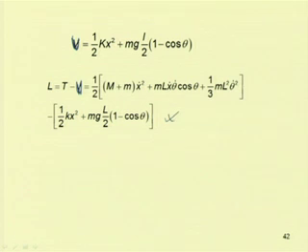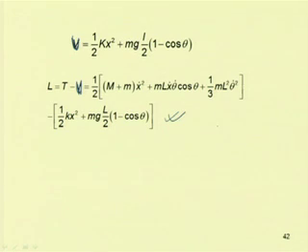So, after getting the Lagrangian of the system, now one can use either the Hamilton principle or the Lagrange principle to find the equation of motion. In this case you may note that k equal to 2, so that is a 2 degree of freedom system. Here I can take q1 equal to x and q2 equal to theta, and by taking this I can derive the equations of motion. So, I can get two equations of motion. Due to the presence of cos theta and sin theta, the equations will be nonlinear.